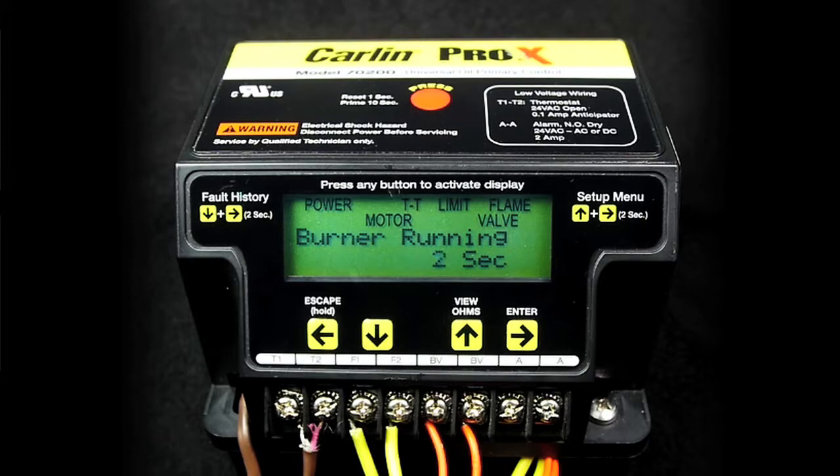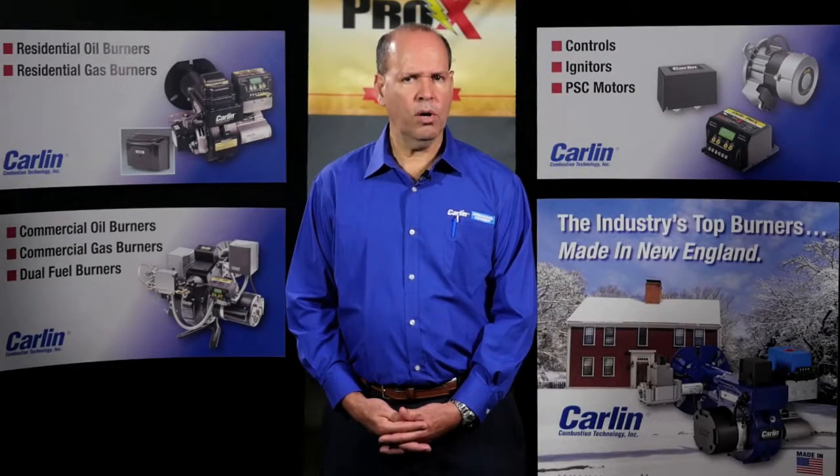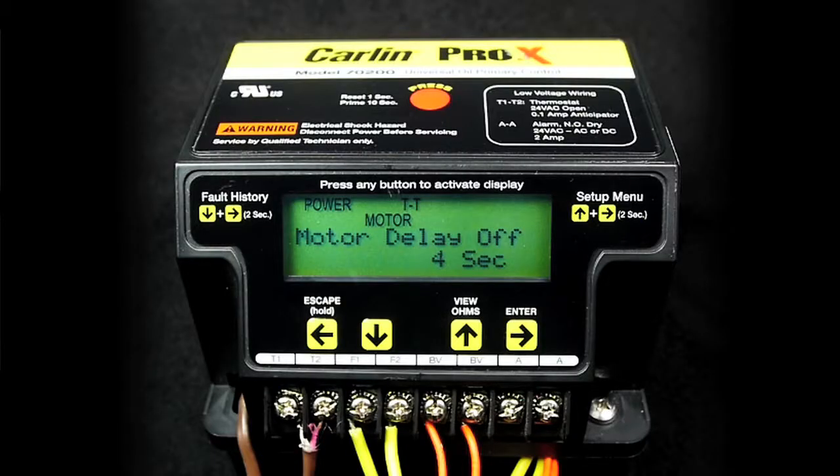When trial for ignition is complete, flame stabilize follows for a short period, and finally, burner running until the call for heat is satisfied. After the flame shuts off, motor delay off cycle begins and will count down until the burner returns to standby, no call for heat.